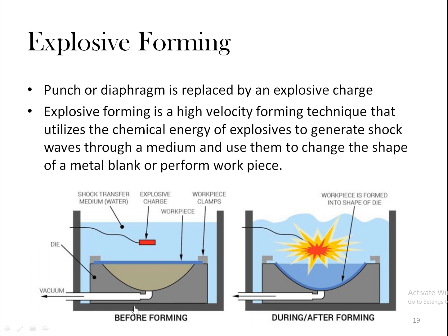Now, as it is said, it's explosive forming, so you need to have an explosive. The explosive is kept at some distance away from the workpiece, and the distance between the explosive and the workpiece is called standoff distance. It is not marked over here, but you should remember this. Now this entire setup is immersed in a shock transfer medium, and normally water is used as a shock transfer medium.